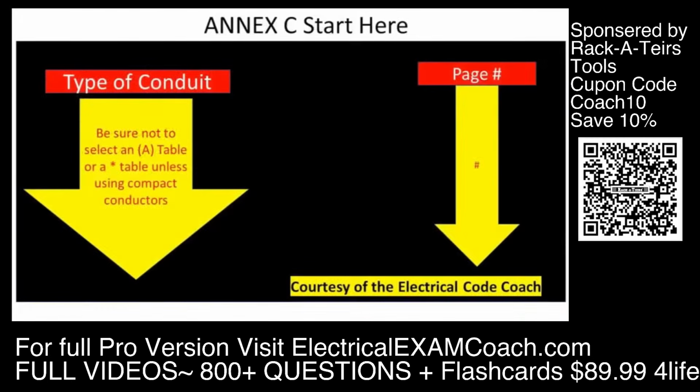So when we get to Annex C, the beginning of it, I call it the Start Here page, because every time you're doing one of these calculations, you're always going to start here if you're using Annex C. Now, when we get there, we always read the black bold heading to make sure that we're in the right table. Great, I feel like we're in the right table. Now, when we head over to the left-hand side, we're going to find types of conduit. And the first one that we come to is EMT, electrical metallic tubing. Now let's look at the second one that we come to.